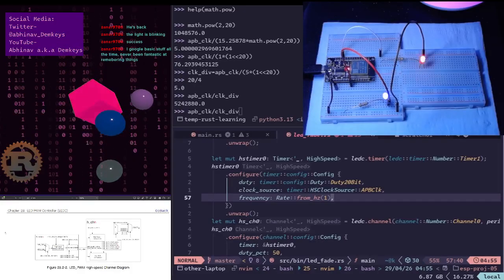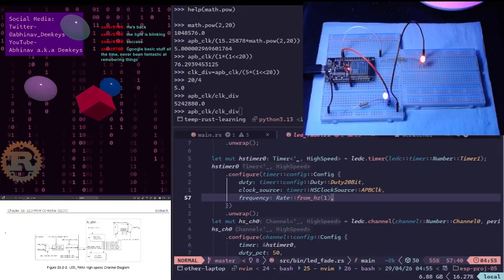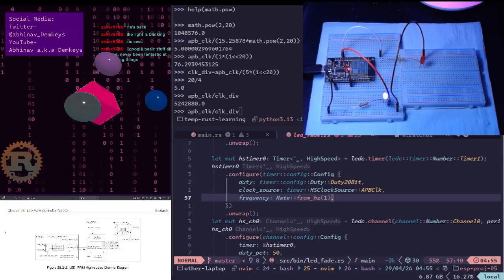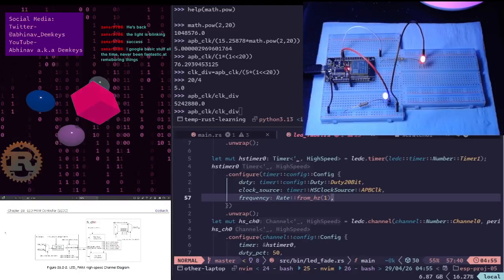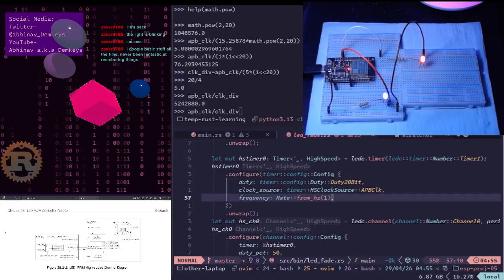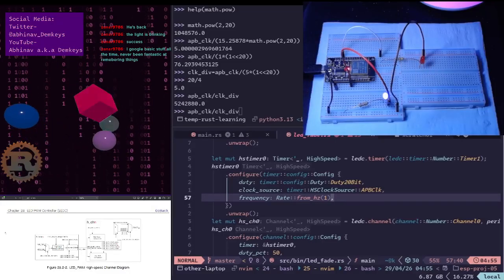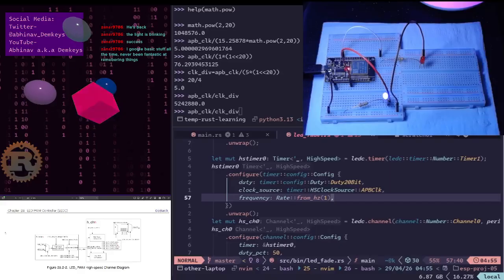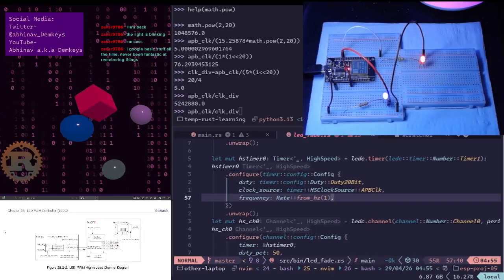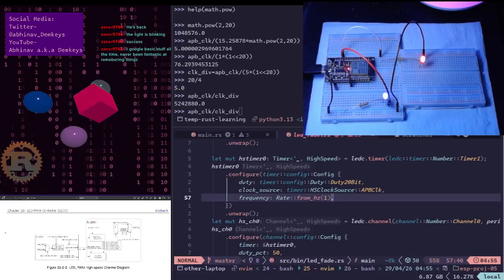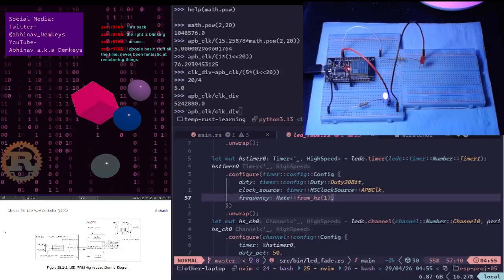So all of this is essentially still running. That's wild, dude. Because now the dots are starting to connect in my head that all of this is running off of that main clock source signal. It's just that as we divide it down, we are telling hardware that's later on down the line when exactly it's supposed to count, when exactly it's supposed to consider one tick has happened. And that's kind of crazy to me.